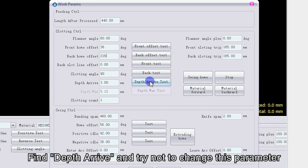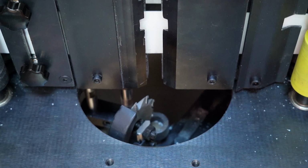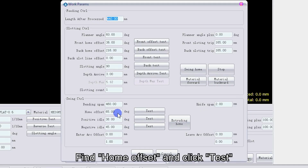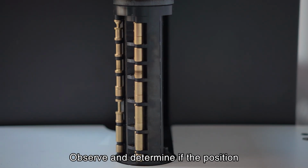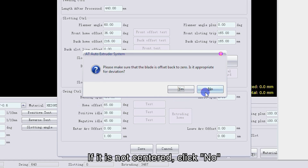Find depth arrive and try not to change this parameter, but click depth arrive test once and click yes. In-depth debugging completed. Find home offset and click test. Observe and determine if the position of the rotary bending blade is centered at the discharge port. If it is not centered, click no.